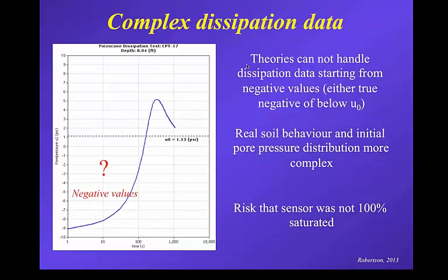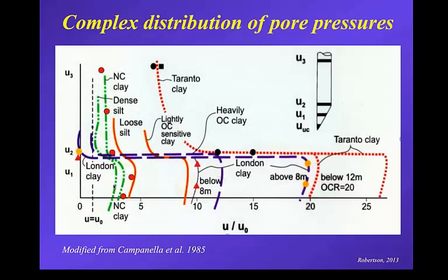And by doing that, he could predict these dilatory type responses where the pore pressure would initially rise and then fall back. So here there's a comparison with this stiff clay from Italy, Taranto, heavily over-consolidated clay, where the pore pressure would rise and then begin to decay down to equilibrium. And so it requires curve fitting, where you curve fit, assuming different soil parameters for the critical state model and assuming different rigidity index until you match the curve.